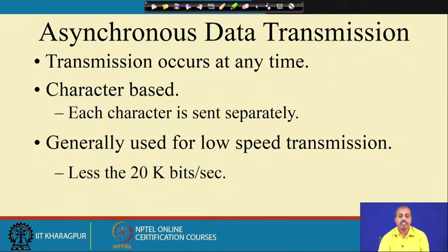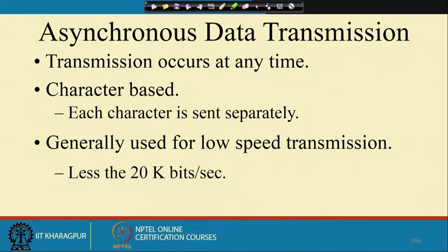On the other hand, in asynchronous data transmission, transmission can occur at any time. So, that way it is better. You do not have that synchronization sequence to be done, and it is character based. Every character is sent separately. There is a particular format for sending the characters, and those characters will have some start bit, stop bit sort of thing, and then based on that the individual characters will be sent. Generally they are used for low speed data transmission, less than 20 kilobits per second.